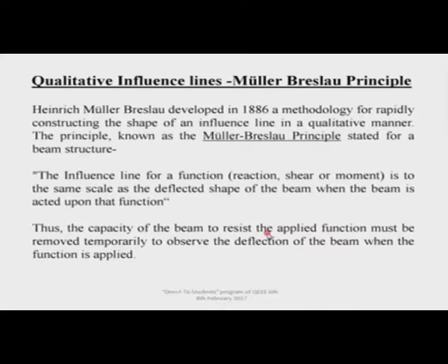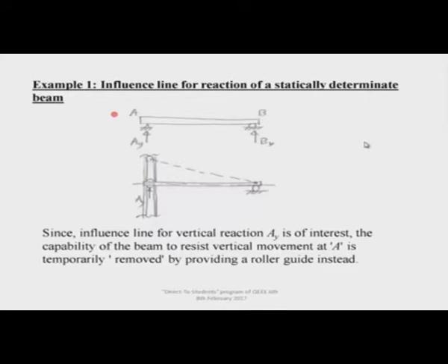What I am probably missing is that if I put a unit load, I would be able to accurately determine the reaction due to that unit load numerically, but that is not possible here. The shape will give a ratio of deflections and deformations at different parts of the beam, and I need to bear with that. So, I lost the quantitativeness, but I may gain better insight into the behavior of the structures for the influence line. Next, let us take an example.